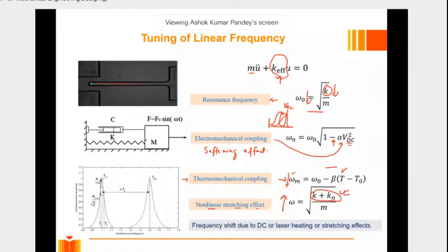So now you see that there are very interesting effects. One is the stretching effect, the thermoelastic effect, the thermomechanical effect, and the electrostatic effect. These two effects reduce the frequency, right? And this effect increases the frequency. Now, if you just try to couple this and this together, you can get very interesting tuning phenomena.